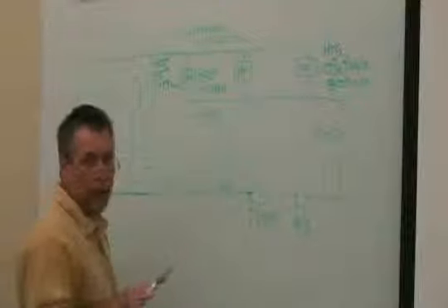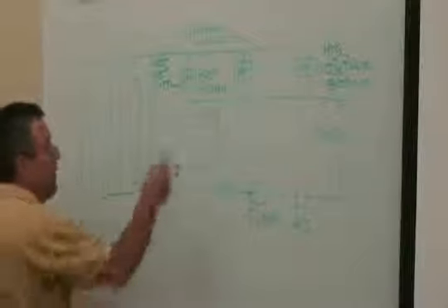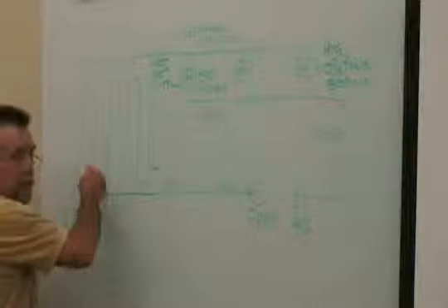So in a geothermal system, depending on your application, if it's residential, you probably want to add supplemental electric heat. But again, it depends on what kind of ground loop you've got. If it's a pond, if it's a ground loop, is it adequately sized, is it undersized, is it saturated, been there 10 years, the water's gone. Those are the things that you get into.